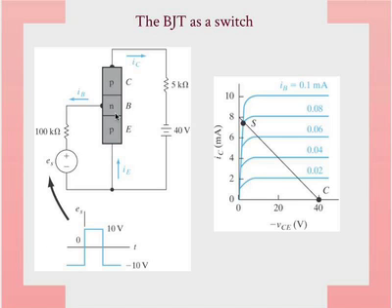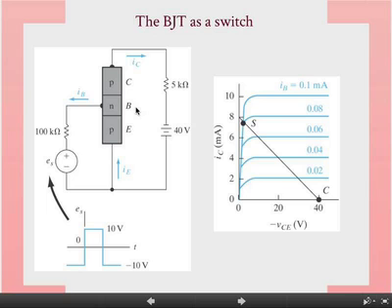two reverse biased junctions. You have something like that. Two diodes, essentially, so the current should be 0. Just write the terminals here. This will be the collector, and this will be the emitter. Basically 0, two reverse biased junctions. That's this point C.